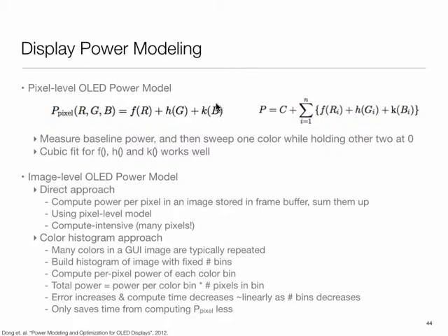So now the way we work with these frame buffers is we send out an RGB value, which is usually 8 bits, so 0 through 255. So it's basically saying the R and G and B indicate the software visible value that the pixel has, and then the actual energy is going to be some function of that. So the red OLEDs are going to consume some power depending upon what the R level is. The green OLEDs are going to consume some power depending upon what the value of G is, and these functions are going to be different depending upon the relative efficiency of those OLEDs.